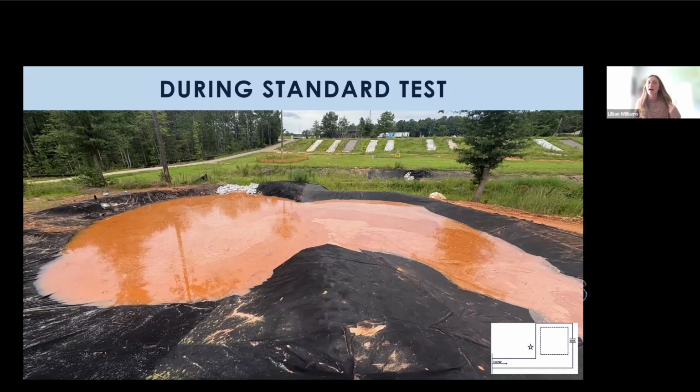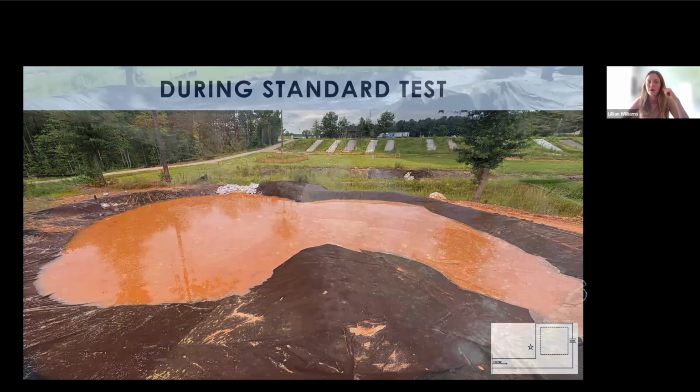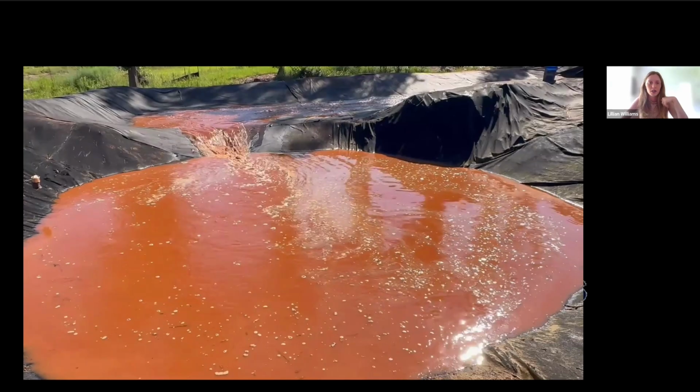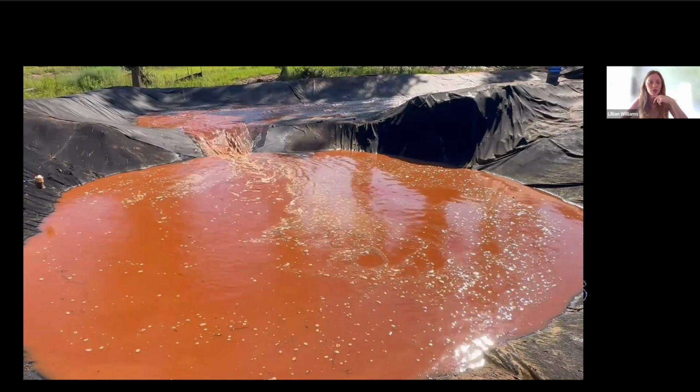You can see a unique aspect to this was that in the basin, it would overflow back into the channel and create more storage volume, which lended to the impoundment benefits that you saw during silt trap testing, because the water would slow down way up here and then make it in. But this was during or near the end of a test, so it took a while to build up this volume if it wasn't already there. This is a picture of it hitting that 90-degree turn and coming in to that sediment trap.